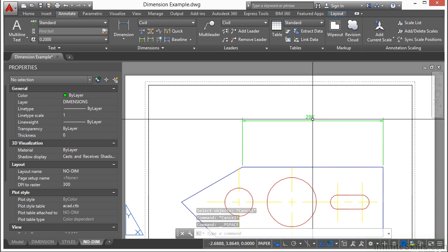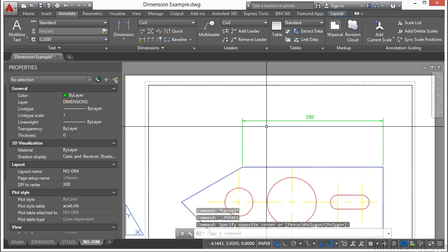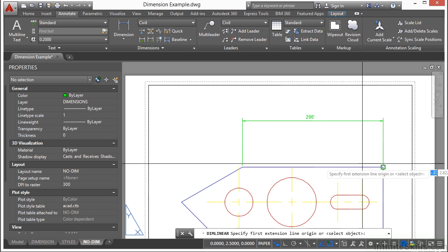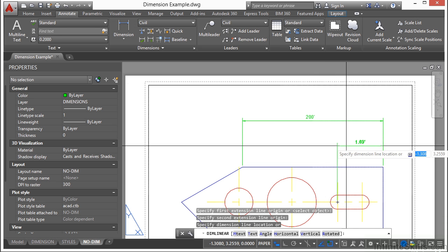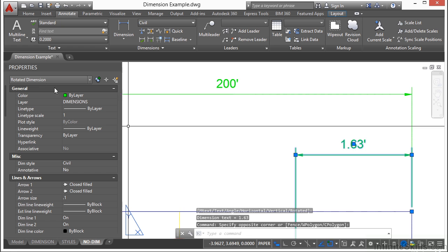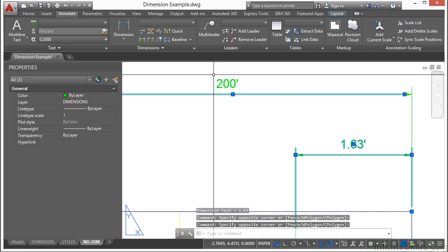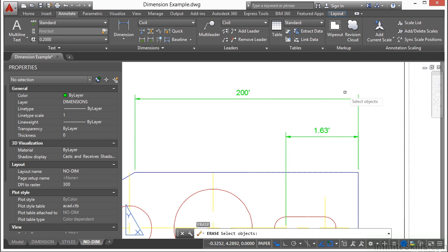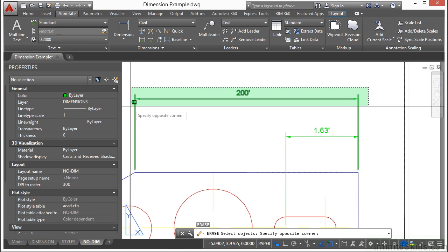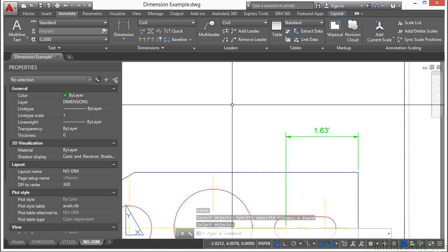Now, there's a difference between setting 1 and setting 2. And a lot of times you'll find older files set up this way, set to number 1. Number 1 turns them back into a dimension object. So now when I create this dimension, I select it, it's a dimension object, same way as if I select the old one. I'm going to erase these to get this out of the way. But this is a setting that you need to use to manually set your scale.